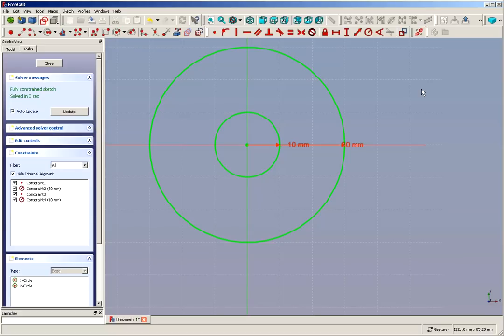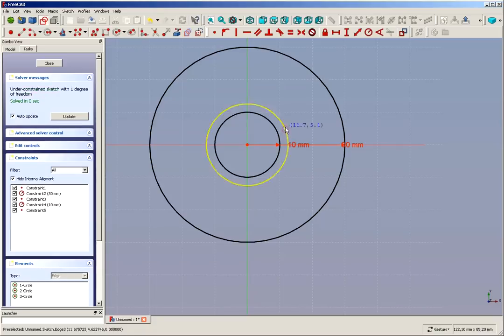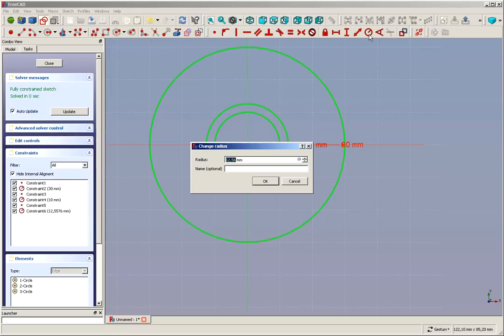Then we want to have some three ingoing circles later on, which should tangent a circle virtually that is a little bit bigger than this circle. So we create a circle number 3 and give this circle a little bit more radius to have a little bit more material around the nut later on.